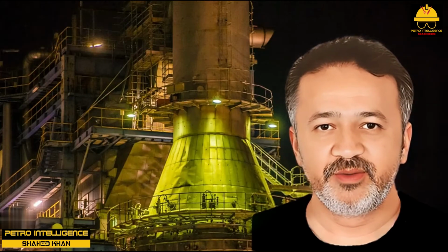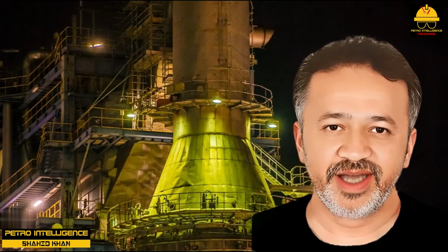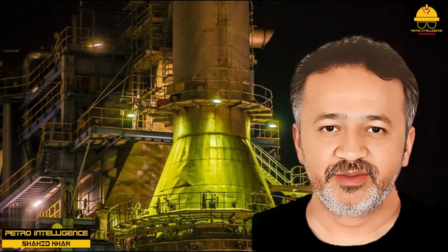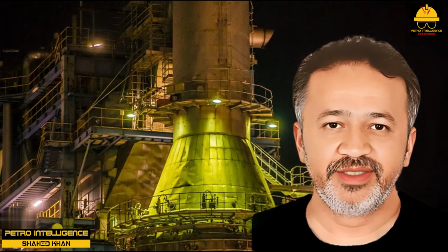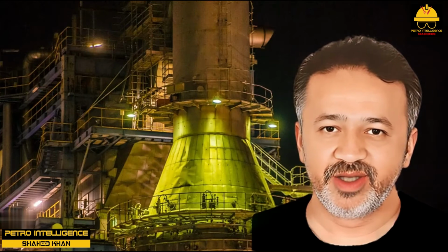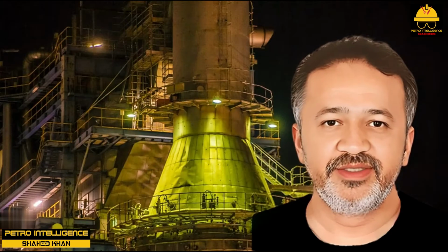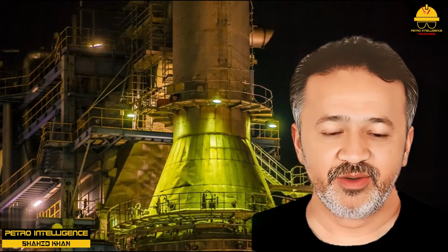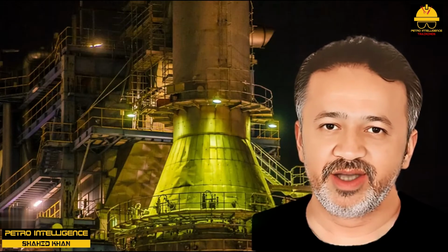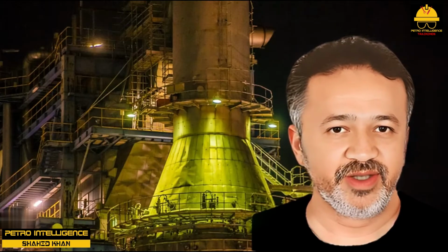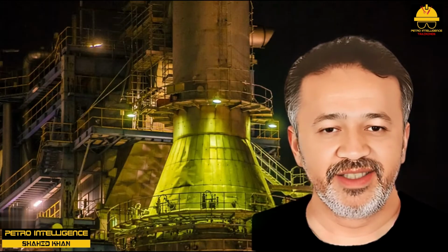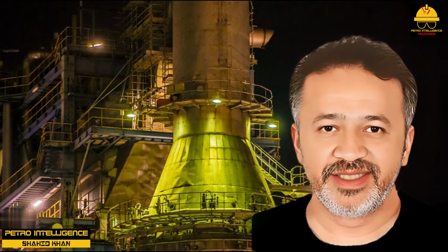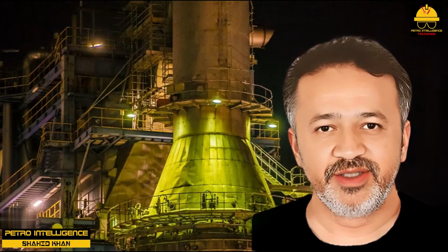The tubes in the firebox or radiant section are made of high-chrome steel capable of withstanding firebox temperatures of up to 2000 degrees Fahrenheit, depending on the severity of operation for which the heater has been designed. Some very high-severity heaters may be designed for firebox temperatures of greater than 2000 degrees Fahrenheit. Note especially that radiant section tubes are protected from overheating by the cooling effect of the process fluid flowing inside them, where flowing is the key word.